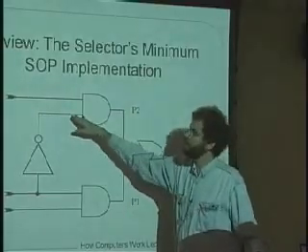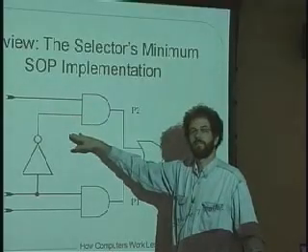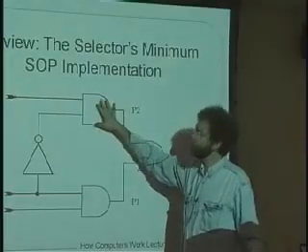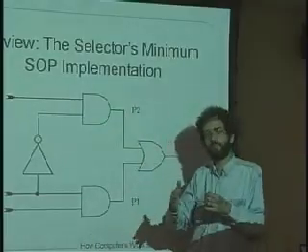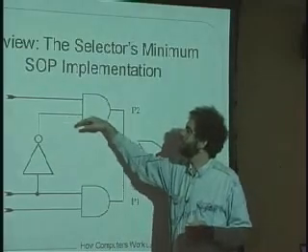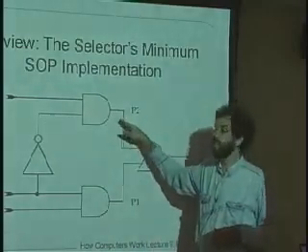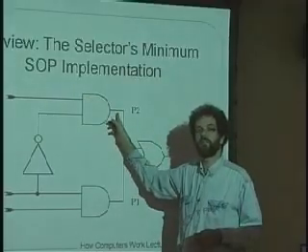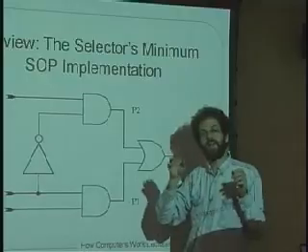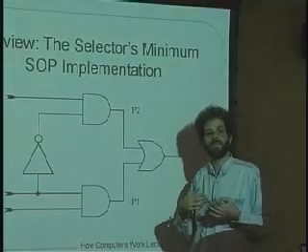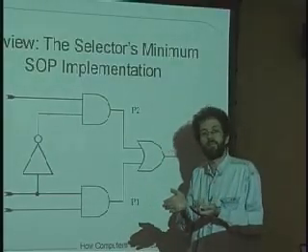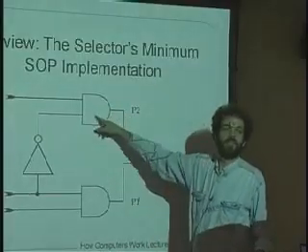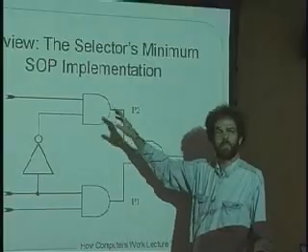On the other hand, if this signal drops down to 0, then whatever A is doesn't matter because the output will be 0. So this is really kind of a gate in the real true sense, where if this is high, it's a gate that allows A to go through, and if the gate is low, it prevents A from going through and forces a 0 on the output. So that's another way to think about an AND gate, and in fact the word gate comes from that, because it's really functioning as a gate to let A through if this is 1, and to just force this to be 0 if this is a 0. Kind of make sense?